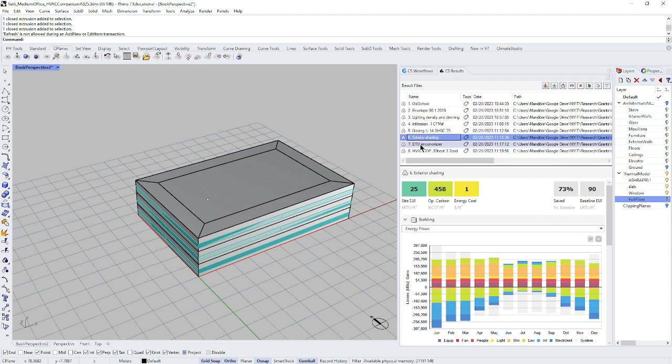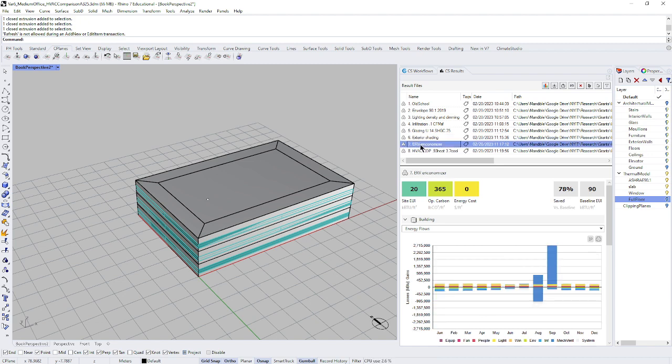Then I added an ERV and then an economizer cycle. Let me explain that really briefly. Right now, before I add the ERV, I was ventilating because I need fresh air, but I was just pulling in fresh air from outside and dumping exhaust air to the outside. That means I spent all this effort getting a specific indoor temperature and relative humidity for my air, and now I'm just wasting that by dumping it outside because I need fresh air.